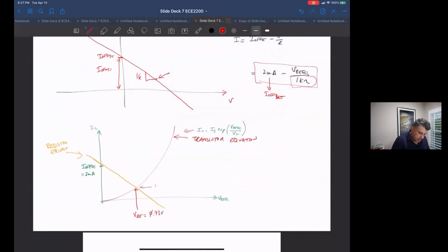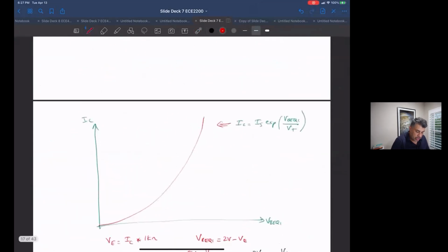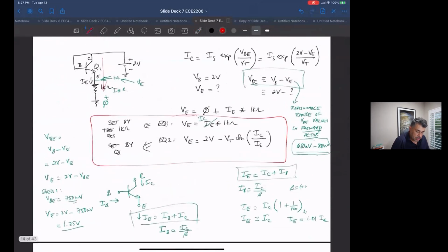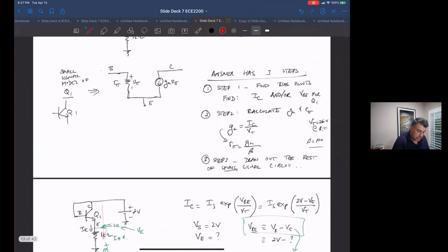And I sub C was 1.27 milliamps, okay? So now, this was just to catch our breath. This was step one, the big step, which was to find the bias point. Now we found it, okay?